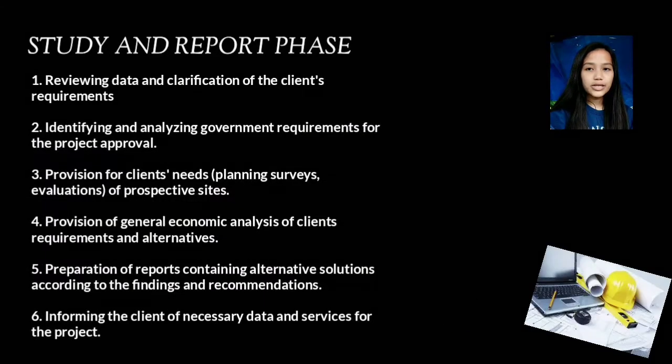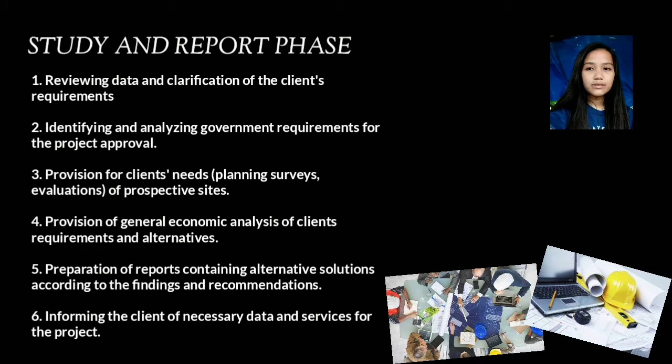The feasibility of a project can be investigated in this phase. First one, reviewing data and clarification of the client's requirements. Identifying and analyzing government requirements for the project approval. Provision for client's needs, such as planning surveys and evaluations of prospective sites. Provision of general economic analysis of client requirements and alternatives. Preparation of reports containing alternative solutions according to the findings and recommendations. Informing the client of necessary data and services for the project.